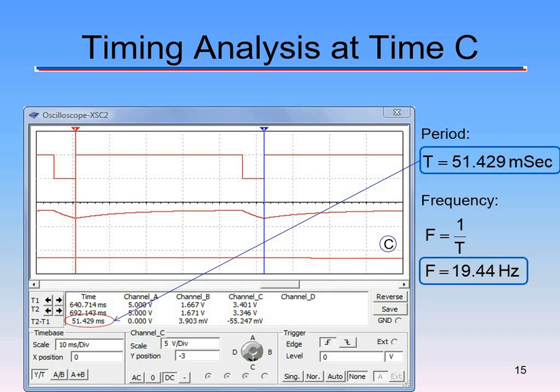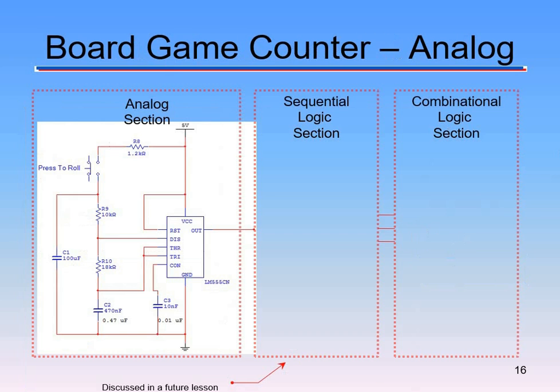Notice how much longer, if we look at the two signals, the clock signal is. See how it's staying high longer, the output, and it's low, okay, for a much shorter amount of time. So now, all right, eventually it's just going to be on at that digit. Look at the capacitor. That's the middle waveform right there, right? Look how long it's taking to charge now, and then when it discharges, it's much quicker. All right, so that third capacitor that we've added in has made a big difference.